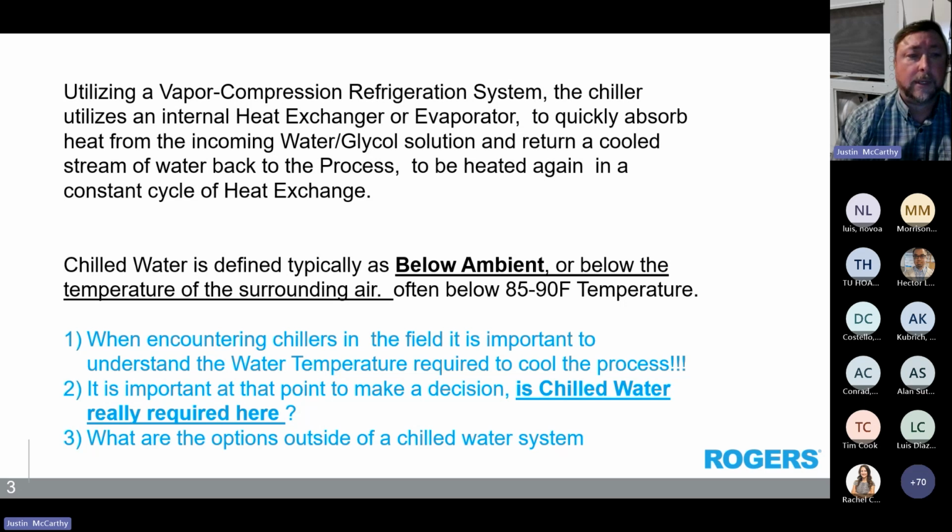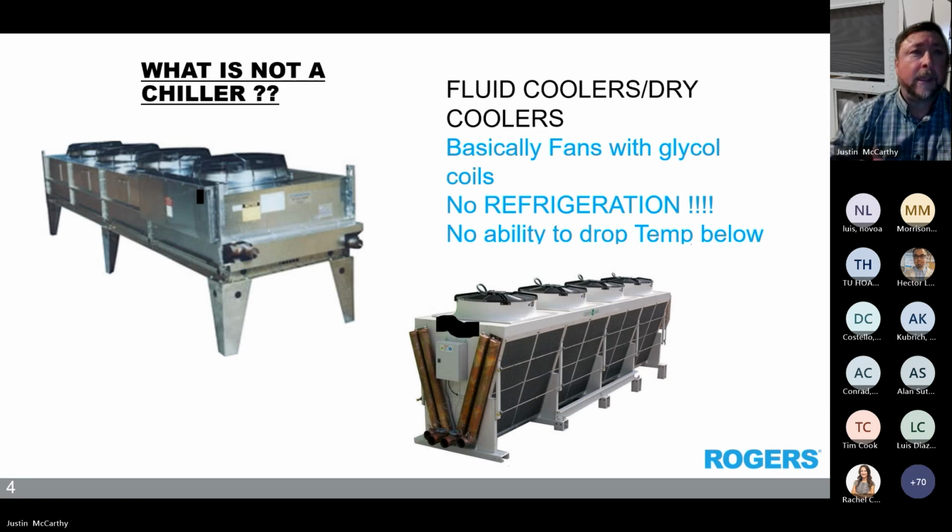When encountering chillers in the field, it is important to understand the water temperature required to cool the process. It is important at that point to make a decision. Is chilled water really required here? What are the options outside of a chilled water system? When trying to understand chillers, it's important to understand what is not a chiller. Fluid coolers, dry coolers. There's no refrigeration.